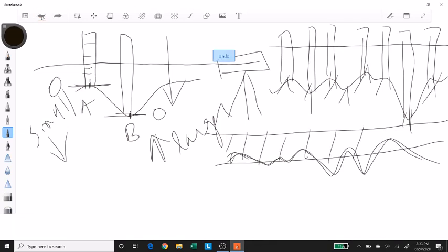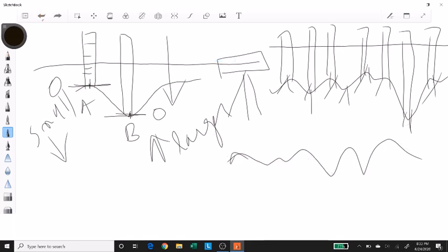On the other hand, I have an option to construct my road over here. That means I'll have to excavate all of this soil. So that's another cost. And another option is to select a profile in such a way that whatever soil or ground I excavate, I'll use the same one to fill it up where filling needs to be done.